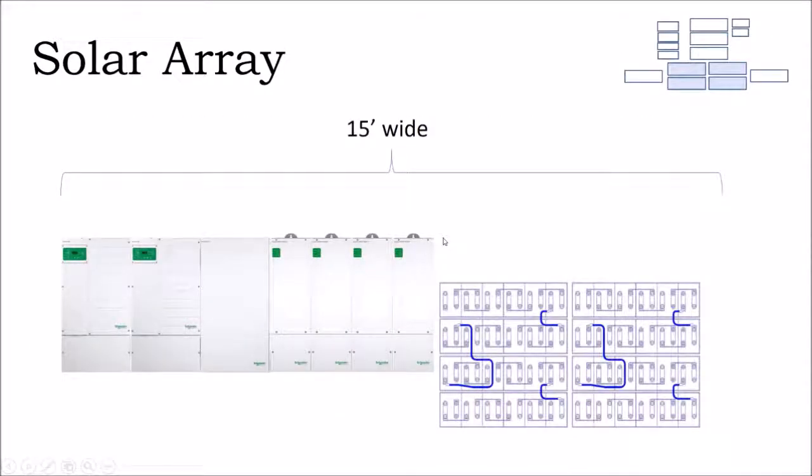And then we need 30 inches in addition to that. So what we really need for a code compliant room for the minimum space requirements of this electrical equipment is really a 16 or 17, actually an 18 foot wide room.